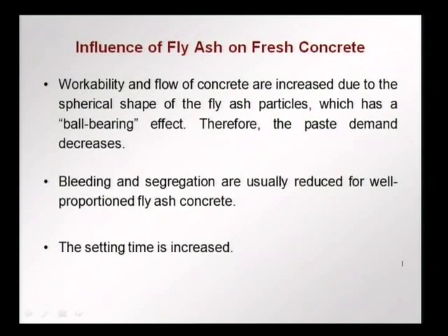Fly ash helps in the fresh and in the solid concrete or the hardened concrete. In the fresh concrete, because of the spherical shape, we have something called a ball bearing effect, where the flow is increased, the workability is better, and therefore the cement paste content decreases. Also we have less bleeding and segregation when we have a properly designed fly ash concrete. Again, because there is less bleeding, we have to take care of the curing, but we get a more consistent, more workable concrete in the case of fly ash concrete. The setting time is also increased. We can use the concrete for a longer time before placing.